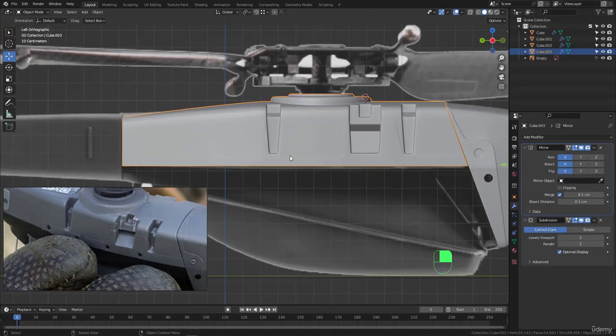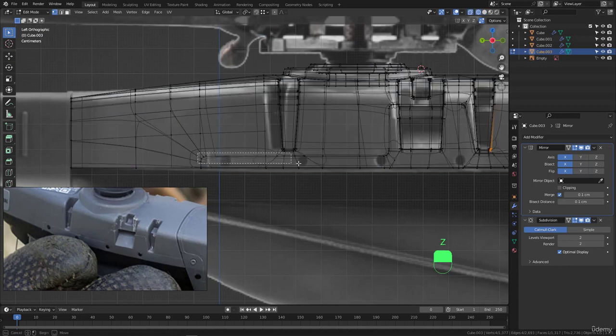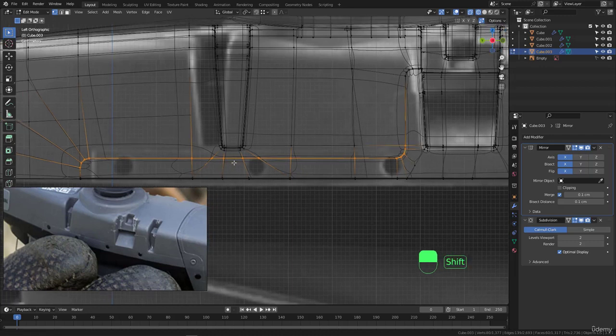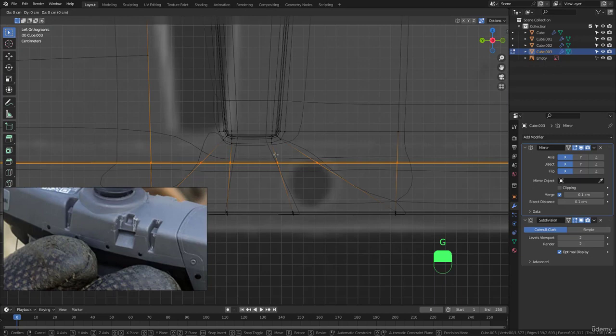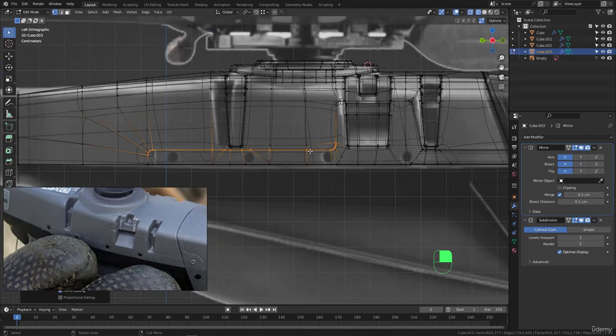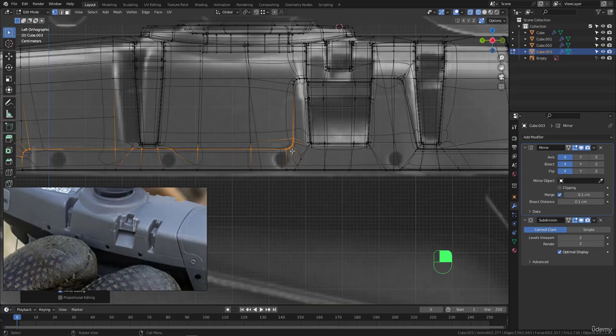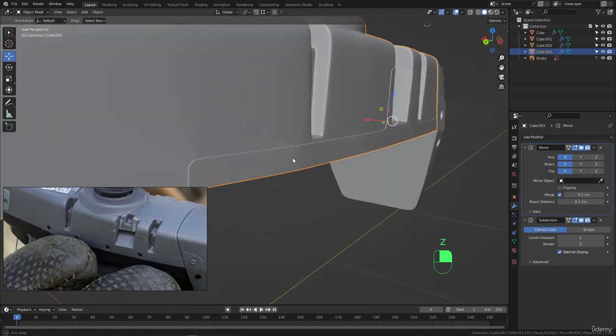To do that, we can tap into edit mode, go to vertex and switch to wireframe, so we can grab all of these vertices. It's very easy, just move them up. Let's hit G then Z and move those up almost right here. I think that will work, and they are almost aligned. That will be okay. Let's go to solid and see what we got so far.